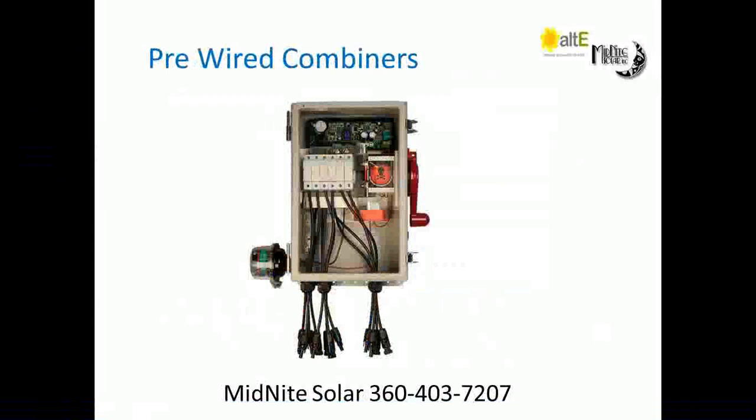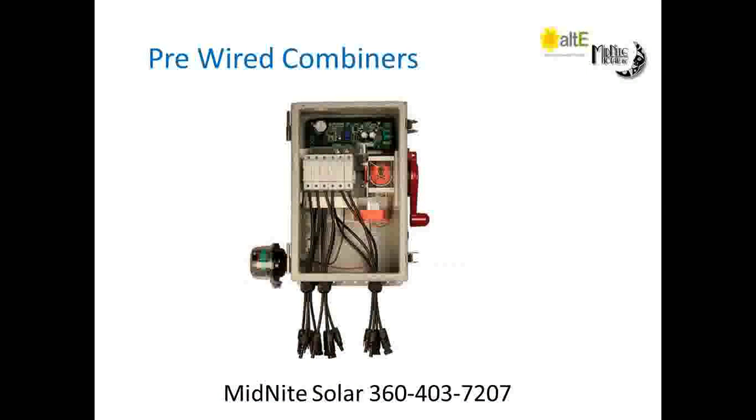This one here, as you see, is Birdhouse compatible, which is another whole webinar, but our new disconnecting combiners interface with our Birdhouse, which is a rapid system shutdown device. It's a single button with visual and audio indication on the outside of the house that wires up to the combiner boxes and battery-based inverter breakers or charge controller breakers and shuts the whole system down with one push of a button over standard Cat5 cable. Definitely something we need to have a webinar on.